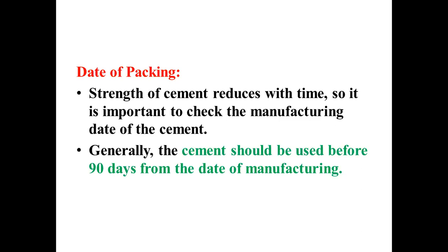So procurement should go stage by stage, and we cannot procure the cement at one time in a large quantity. There is a problem we will face if we procure cement bags in huge quantity: losses will occur, or it will not be workable with the site conditions. So that is about the date of packing.